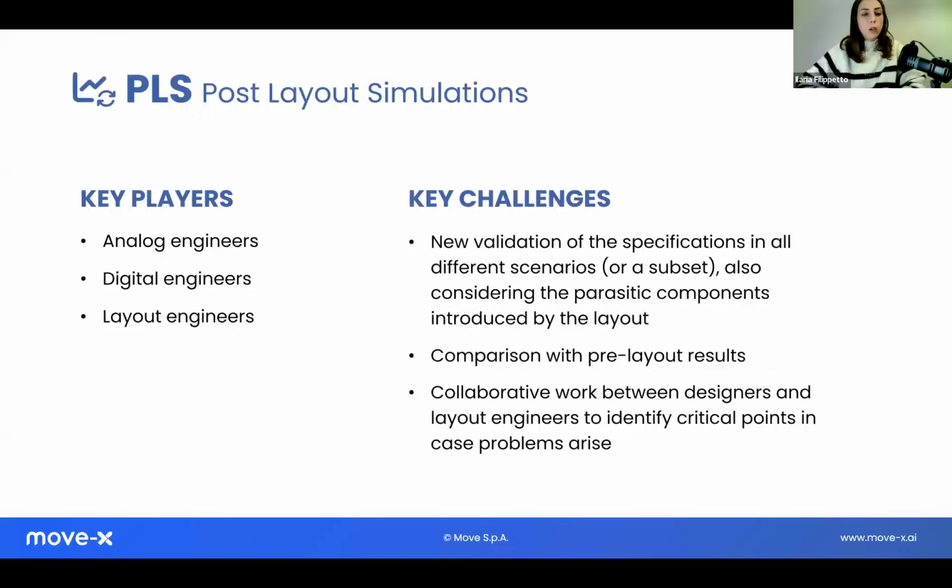Okay, so when the layout of a cell is completed, the designer can proceed with the post-layout simulations. The goal here is to validate all the specifications again, but incorporating the extracted parasitic components in the layout view.